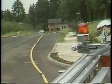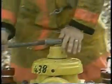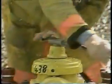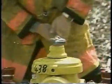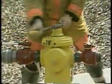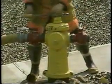When the hydrant operator receives a signal, if visual contact is possible, or feels that enough time has elapsed for the hose clamp to have been secured, the hydrant valve is opened slowly while remaining behind the hydrant. If a coupling fails, or if the threads on the port, which may be rusted or cracked, fail under pressure, the operator will be protected, standing behind the hydrant. The valve is opened slowly to prevent water hammer.